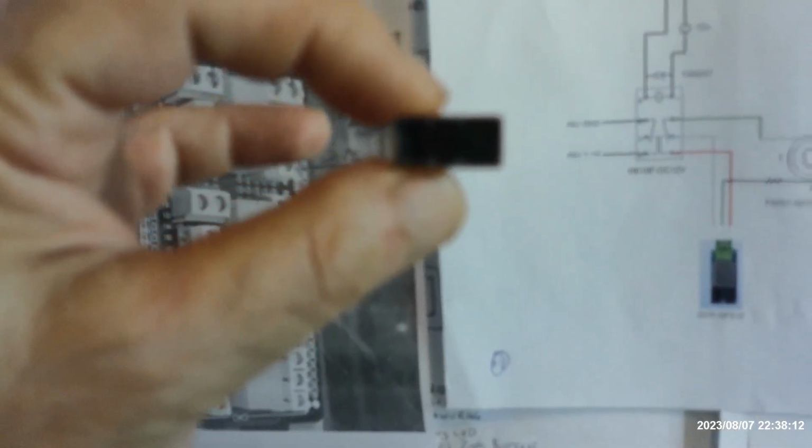And what was happening is I had a 3D printed holder, and I was mounting it on the wall this way, and the stress of those wires hanging down, some of the threads that didn't get soldered, that's why I don't like stranded wire to solder, ended up touching one of the other pins, and that was a problem.